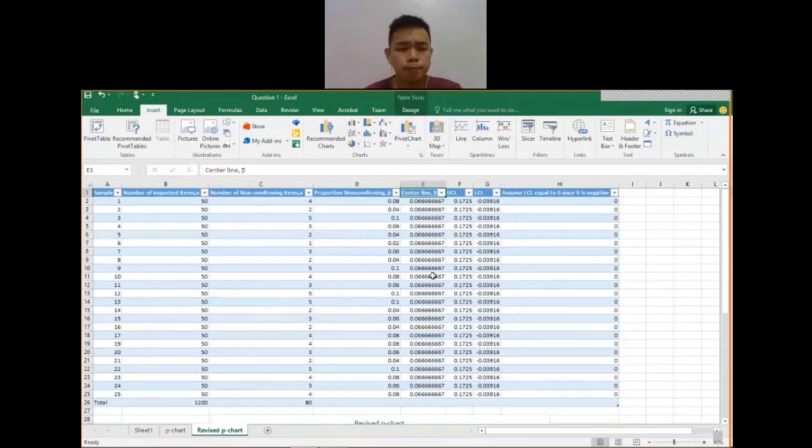So now I do the P chart again. For the revised P chart, I consult the table again and key in all the data given by the question. But this time there is no 18th sample; you can see on this table that I eliminated the 18th sample. Now you can see that I calculate P bar, the upper control limit, and the lower control limit with the given formula from the beginning.